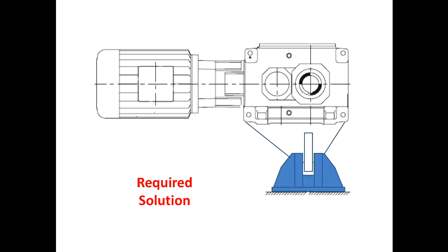Just so everyone in the room gets it, Brian, do you mind if I have a try to see if I can do a free-body diagram for what you've got up there. Big torque being applied. You've got a prismatic joint down here. If this block wasn't there, it's going to stop everything. So we'd have a resisting force there, back up to the shaft, bending. Yeah, because the motor and gearbox is all supported off the shaft.